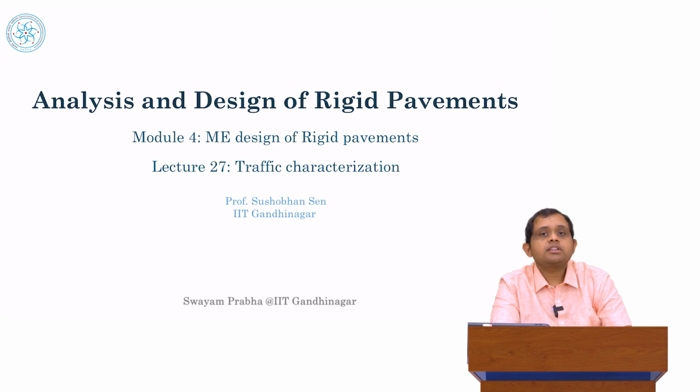If the distresses are less than the targeted performance or the targeted threshold, it's an acceptable design. If it exceeds it, then we go back, we create a new test section, and by create I mean just do, it's a mathematical calculation. So we come up with a new test section, again go back and calculate distresses, compare it to the performance criteria, etc. So design is repeated or iterative analysis, which is why we spend such a large part of the course actually focusing on analysis.